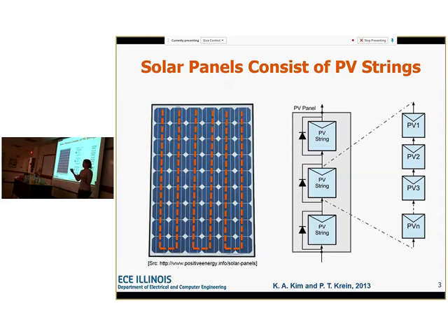Then around each of those strings, you have a bypass diode, which, if you're familiar with photovoltaics, is what they put around it to attempt to protect against hot spotting. But some of the modeling research that I've done has shown that you can still get hot spots forming, even if there is a bypass diode, which has been shown in a number of studies. So this is still a problem. It's not completely conquered by the bypass diode, although it does help. So we're always dealing with strings of PVs, and really it comes down to this. This is the culprit.